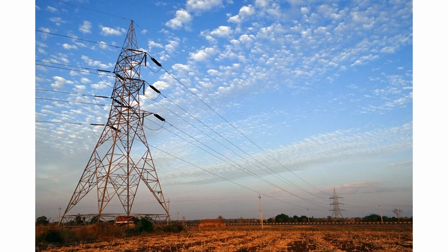In my region, long distance power transmission is over 220 kilovolt, 110 kilovolt or 66 kilovolt tower lines from the generator to substations. From the substation, local distribution is with 11 kilovolt high tension lines and then with 440 volts low tension lines. All these are three-phase lines. A single phase of low tension will give about 230 volt for home use.